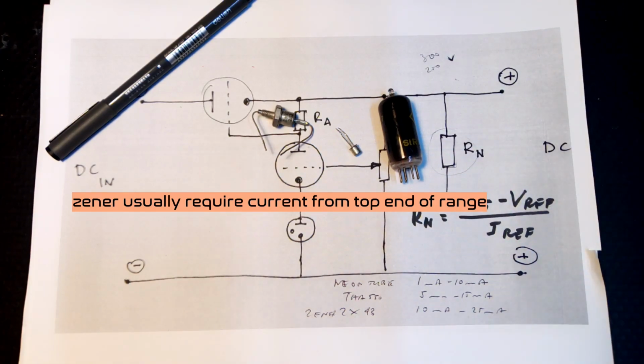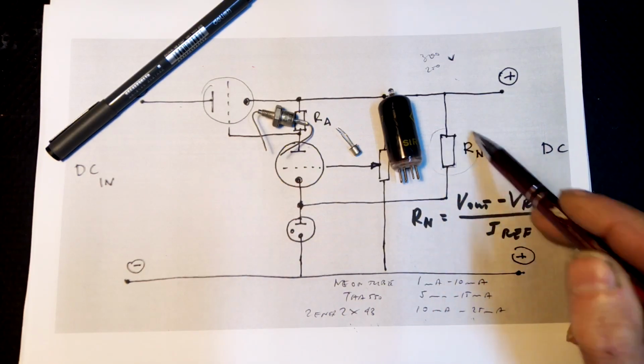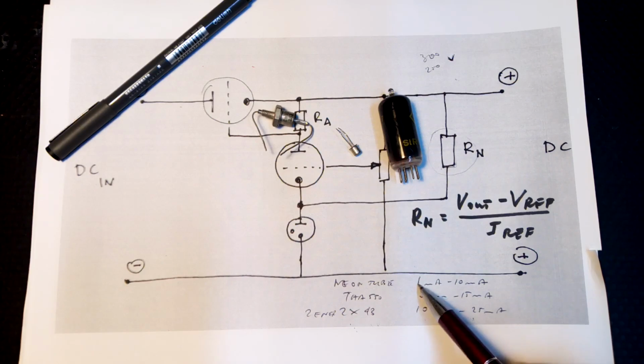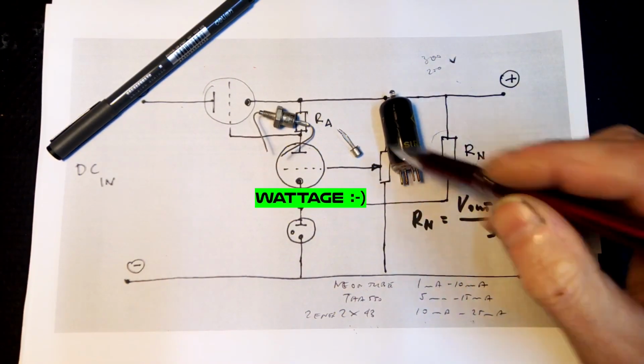And from experience, not only mine, this Zener requires rather higher current than lower. So of course with the neon tube we have the smallest current and the biggest resistor here. With this one we are around the same, because we never run it at 1 milliamp, we always choose a bit more. And with the Zener diode we use the biggest resistor in terms of watts of these three elements.